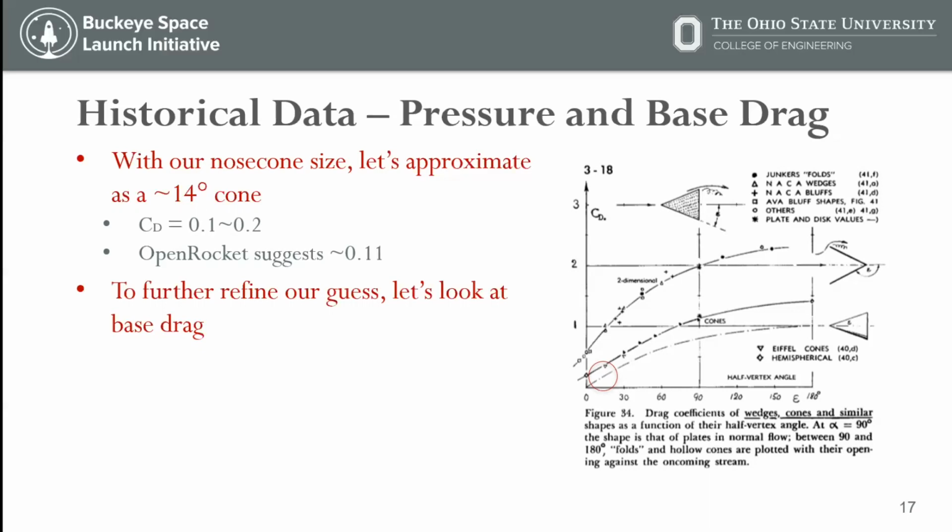Experimentally, it was found, and there's probably a full-on derivation for it somewhere, that it will minimize drag for, I'm going to go with area, but I'm not quite sure off the top of my head. I know about 3 years ago, the Aerodynamics team for 30K looked into it, and that's why they chose von Karman for the 30K rocket. But they also looked at all the flight regimes, subsonic, transonic, and supersonic, and von Karman just happened to be the best throughout all of them. It performed pretty well.